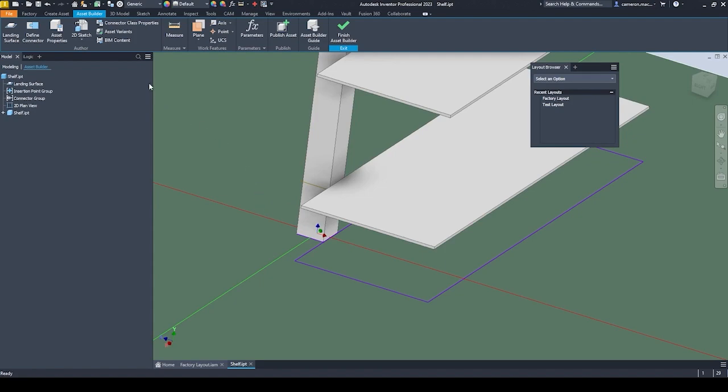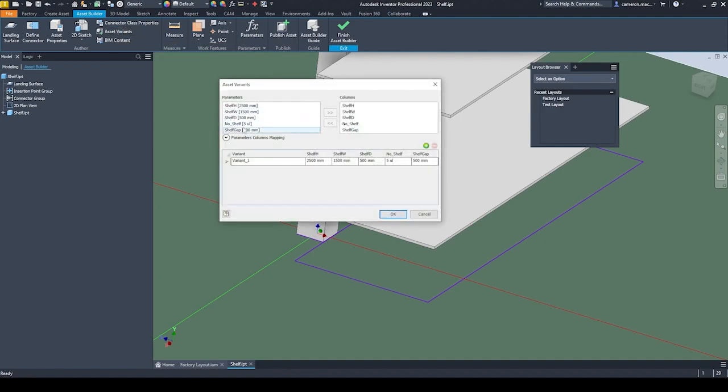We've also got the ability in here to start adding variations of this. So as you saw earlier, we've got certain components that can change in their sizing, whether it be the height, whether it be the width, whether it be the number of feet, for instance. We've got the ability to come in and set variants from inside here, where we could come in and grab any of the parameters inside of our part. So if we had created this file with variations in their parameters, or we could essentially retrospectively add those in to our set just by ensuring that these are key